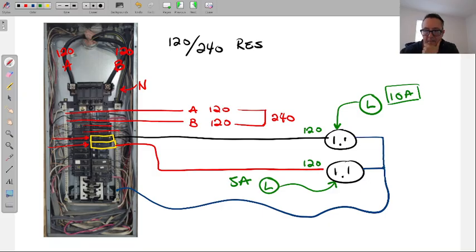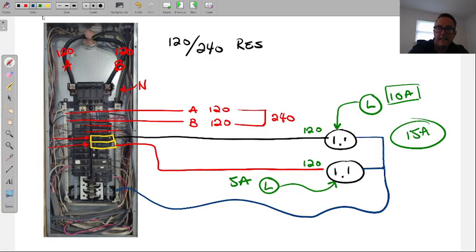15. All right, we got 15 over here. Or 20. Does anyone have a different number? Not 20. That's the amperage code. There's one other possible number, the neutral? 15, because what I'm assuming you are doing is one load has 10, the other one has 5. Right? Yes. But is it just 20?